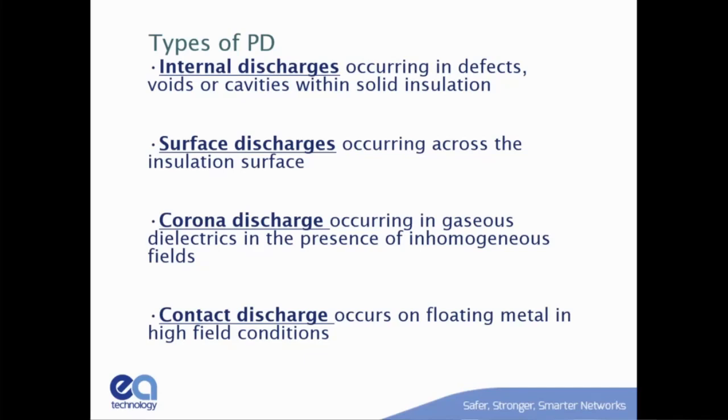It could blow up the next day. And that's why you need to be able to find internal discharge. Fortunately, internal discharge is more rare. It's more related to manufacturing defects than any kind of installation or wear problem. It also moves the slowest. It grows the slowest. It takes the longest to lead to failure. So we've got a little bit of time.